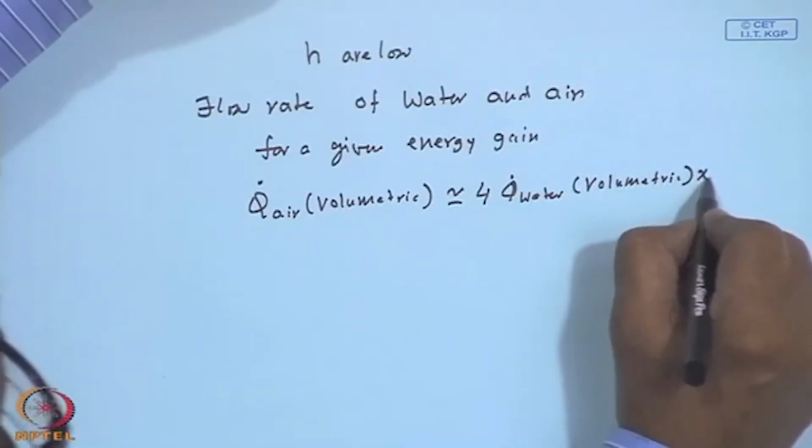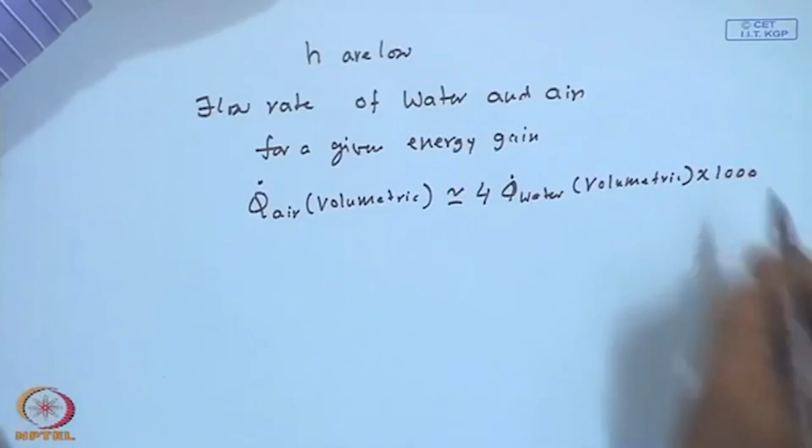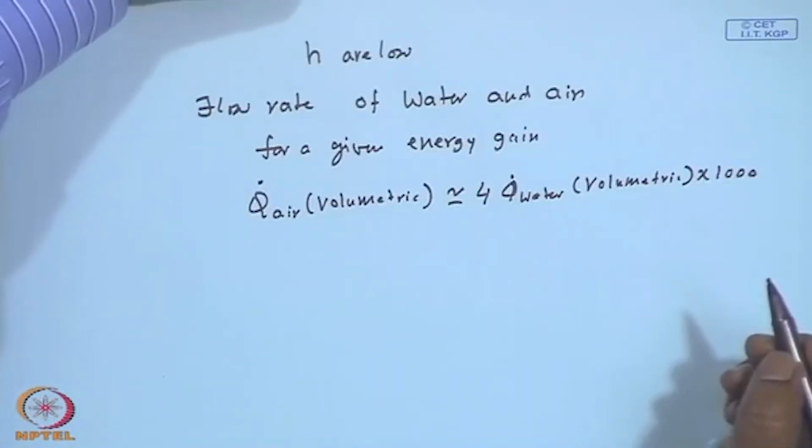You can see the specific heats of water and air have a ratio of about 1/4. The specific heat of air will be 1/4 that of water, and the density is 1/1000 that of water. So, if you calculate for a given m c p delta T, you need a volumetric flow rate of about 4000 times, or a mass flow rate of 4 times, that of a corresponding liquid or water heating system.